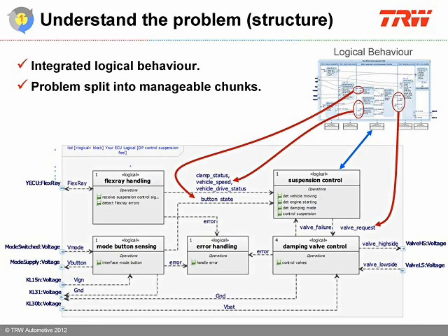A structural view of the ECU function in terms of logical blocks and flows is created using an internal block diagram within the logical architecture. Flows and flow items are used to define the information, materials or items that flow between the logical blocks, as indicated by the red arrows in the example. The flow items are also used to specify the input and output parameters of the logical block operations.